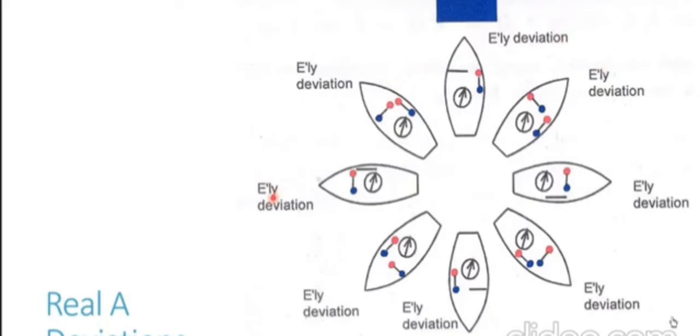And in the definition of coefficient A, we have seen that it generates a constant deviation irrespective of the heading. So we will now see how this deviation remains constant over all the headings. Let's first understand how this easterly deviation is generated with the ship on a northerly heading. I'm going to zoom into this diagram with the ship heading north. We have a fore and aft longitudinal and an athwartship beam. There is no induction on the beam right now because it is at right angles to the Earth's field, and there is maximum induction in the fore and aft longitudinal. So let's now zoom into this.